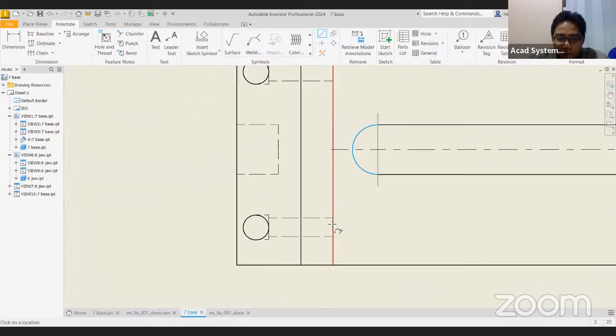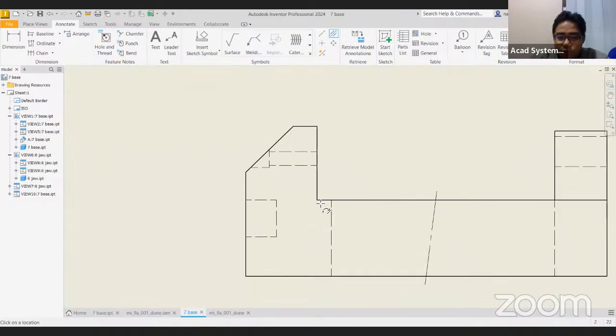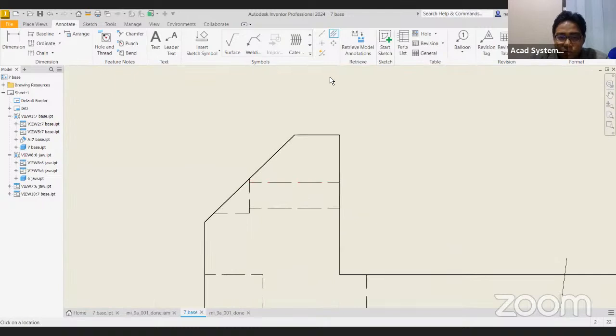If you don't currently have the points that you can snap into, the best method that you can use is the center line bisectors. This will allow you to select both the lines, and it will divide the line automatically. So for this case, I can just use these bisectors. Select the second line, and it will create the line at the middle of the two lines. And if I want to, I can also re-edit the lines. So I can just make it slightly longer.